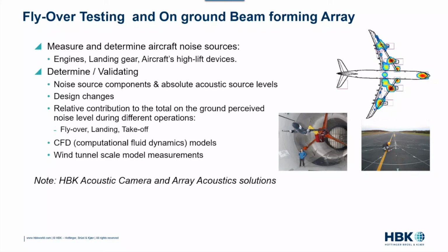What I wanted to point out here is HBK has got several solutions from an acoustic standpoint. You can do wind tunnel testing. You can have an acoustic array on the ground and fly the aircraft over and do beamforming, or use the acoustic camera. Because just because it makes noise doesn't necessarily mean you don't have to figure out where the noise is coming from. So these different tools can help you better understand your aircraft and where the acoustic excitation is coming from.